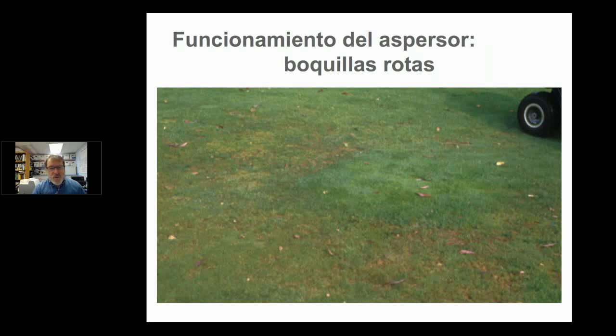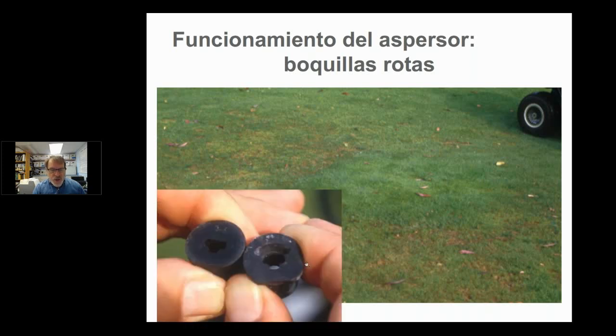This is an example of where that was collected. We were looking at this poor performing turf all around this head, and we're trying to figure out what was going on, and we found out that the cause was distribution. When we looked at the irrigation head, we noticed that the backup irrigation nozzle was broken. There were some of these nozzles that should have this flat dispersing portion on the nozzle. They had been knocked off, or they had been broken. And this type of thing resulted in the head throwing water over that donut sort of area near the green.